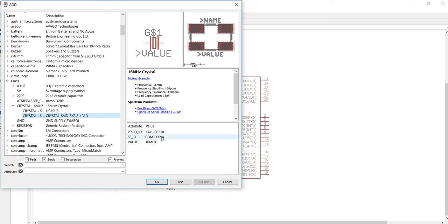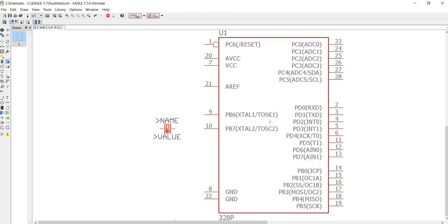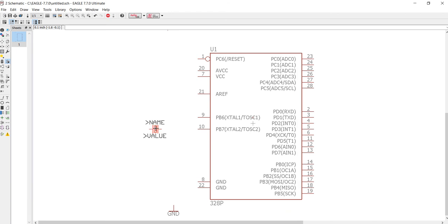And you can see these were parts that I took from the SparkFun library, which I suggested. Again, I would suggest you download the entire SparkFun library. It has a lot of fantastic parts. They're usually accurate and work very well. So it gives some part numbers in here, so you can easily order these parts. So we're going to stick with the through-hole version just to make it easier to solder up if you did choose to actually do this.